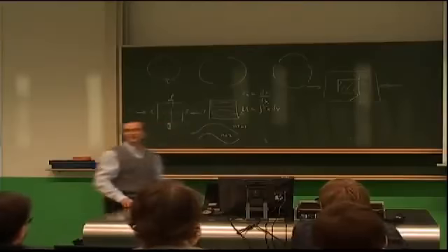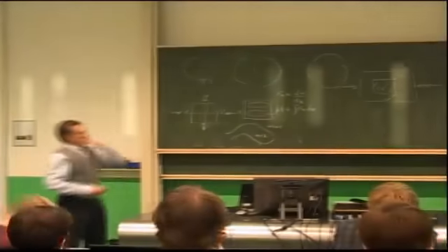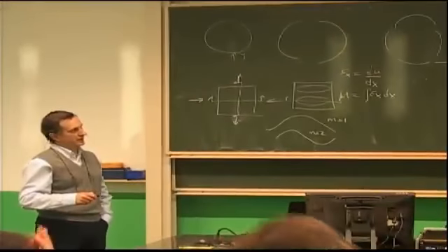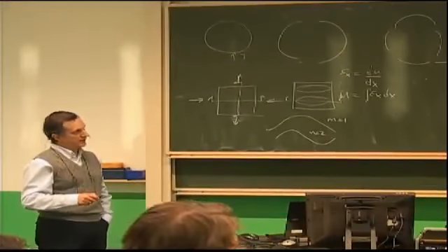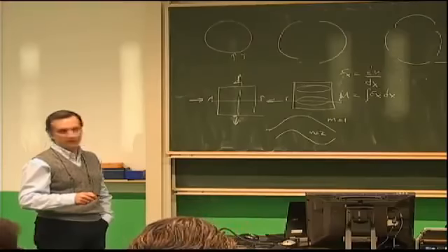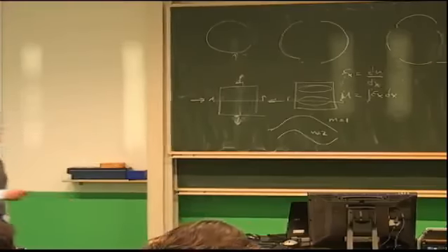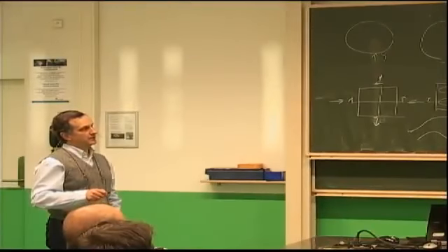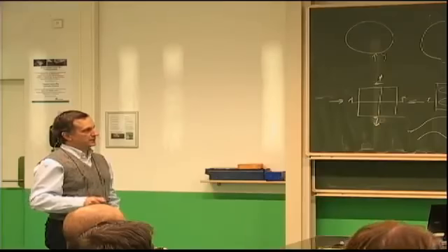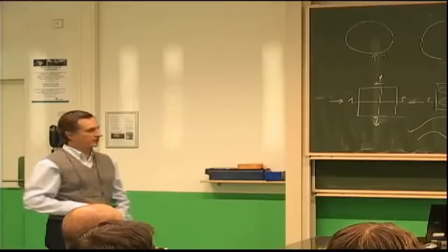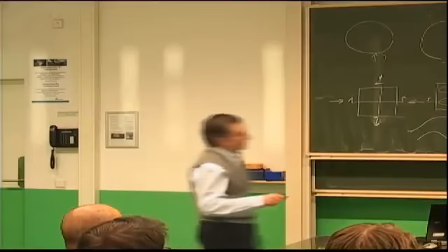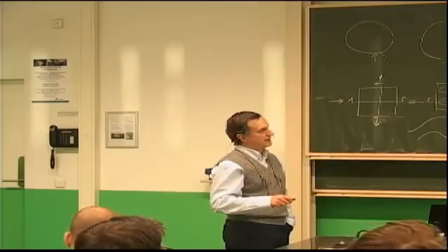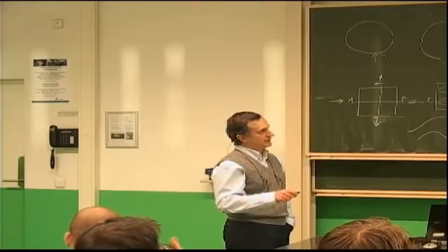Miracle. All right. So this is the case that involves both the uniaxial compression, the compression in one direction, and tension or compression in the other, expressed by positive or negative values of K. If I only have single compression, then Ny is 0, which means the K shown there would be 0. And therefore, this is my buckling load for uniaxial compression. And if I look at this one now, this buckling load is a function of M and N.